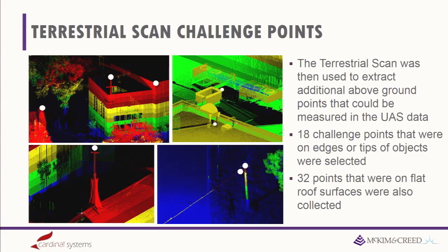So as I said, from the terrestrial scan, we extracted additional points that we were going to use to test, to verify this method of stereo compilation. And we picked points that we knew in image-derived point clouds traditionally don't show up well. Some wires, you already saw a profile of the cross, some rooftop features, and things like that. And we extracted 18 points that way.